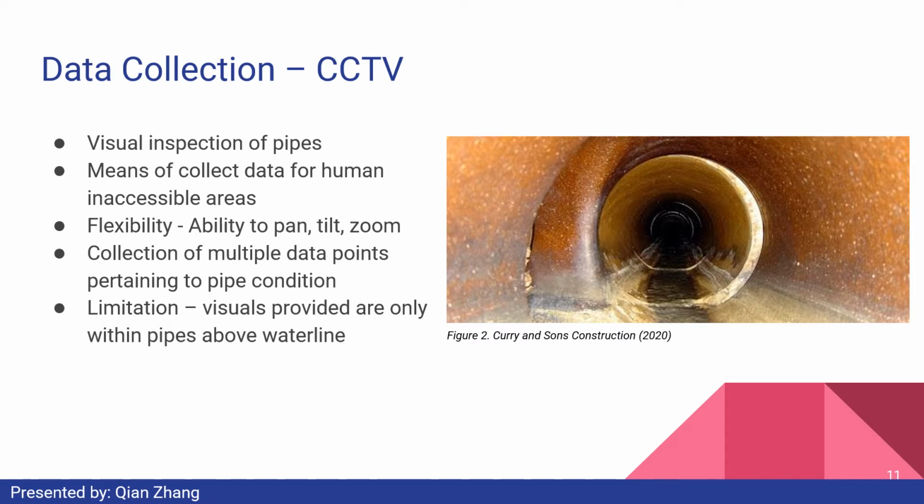Furthermore, multiple data points can be gathered, including the presence of sediments and debris, pipe sags and deflections, evidence of cracks and leaks, as well as their locations. The limitation of this technology is that CCTV cameras can only be deployed within the pipeline above the waterline.